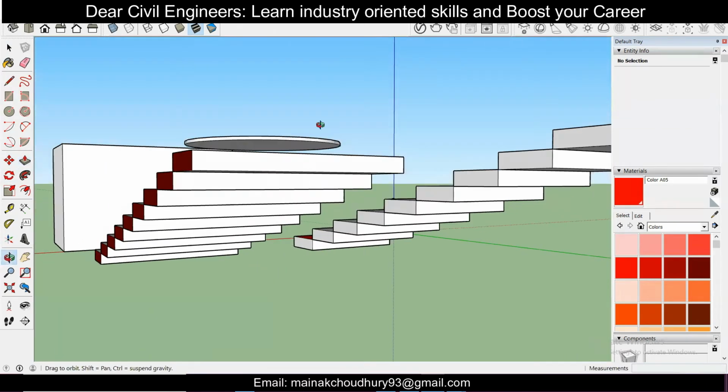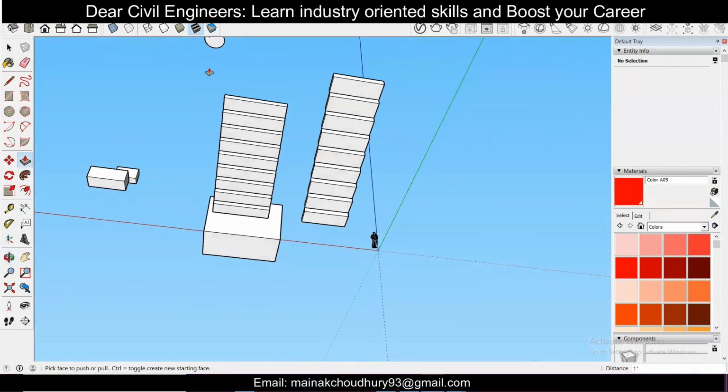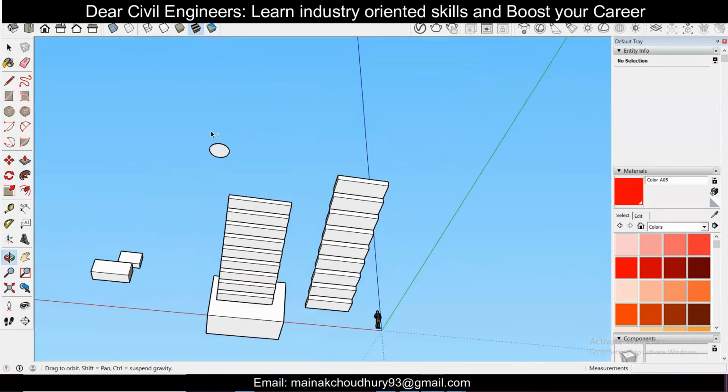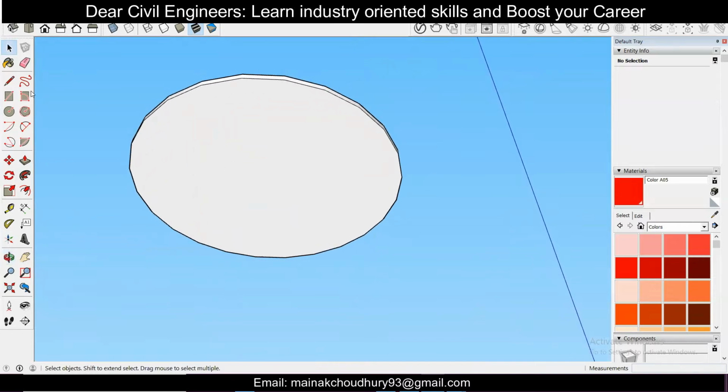So we'll go to the bottom view. I'll go to the select tool first, and then I'll use the pan, and then zoom in with the mouse. And after that, I want to place a circle here. So this is the blue axis. I want to place a circle here. Let me place a circle of radius, let's say, around 1 inch or 1.5 inches.